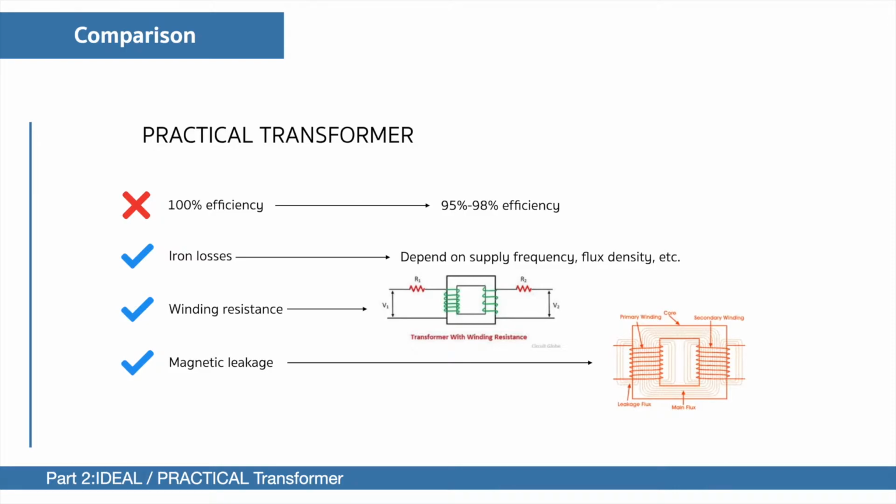Leakage reactance. When we provide supply to the primary of the transformer, an EMF is produced in the primary coil since electrical coils are inductive. So, it induces magnetic flux, but what happens to the flux lines which are small circles at each side? Their circles are not large enough to pass through the core, so it wastes magnetic field and hence energy. So it needs to be considered as some sort of leakage flux in the transformer from primary to secondary. Although leakage flux in a transformer is quite small compared to the main flux, yet it cannot be ignored.